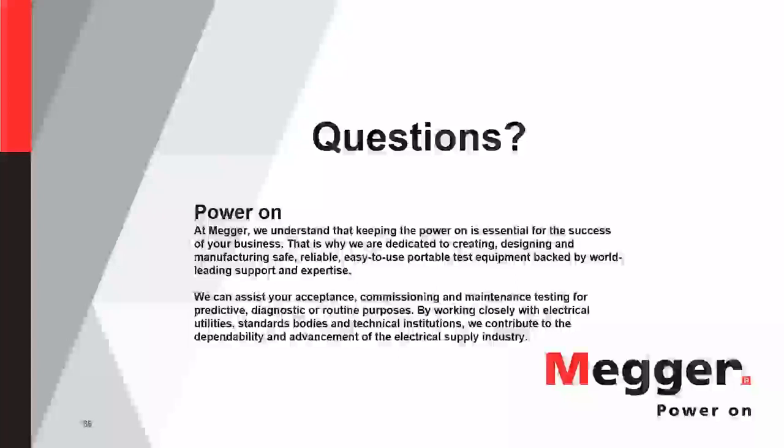from a lot of times from an IEC world, 50 hertz, and so that's half a cycle. So you could even do 10 milliseconds or 20 milliseconds afterwards. And if you think this breaker, it has a 2-cycle, 3-cycle, 5-cycle interruption. So it's guaranteed to interrupt in there.